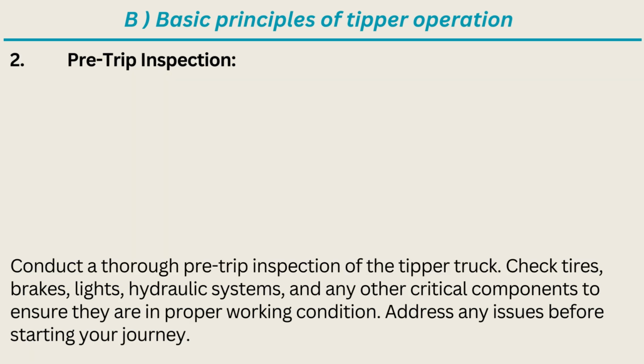2. Pre-trip inspection. Conduct a thorough pre-trip inspection of the tipper truck. Check tires, brakes, lights, hydraulic systems, and any other critical components to ensure they are in proper working condition. Address any issues before starting your journey.